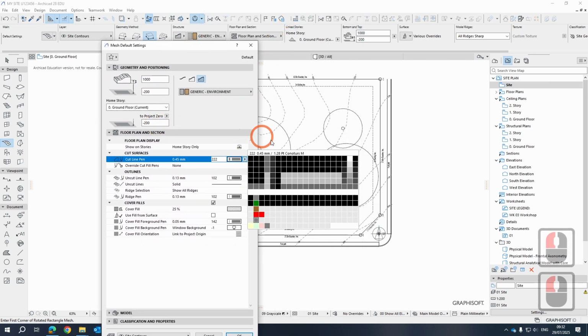For now, I'm just going to make sure that this will work well with my pen styles. Typically, you're going to try and categorize this information, but for now you'll see you've got all these other fills and we can add these on later. You can see there are some layers that we can maybe use, but this does take a bit of time to get used to. So I'm just going to use the drafting layers for now. For cut line, I'm going to use the cut line in drafting for now.